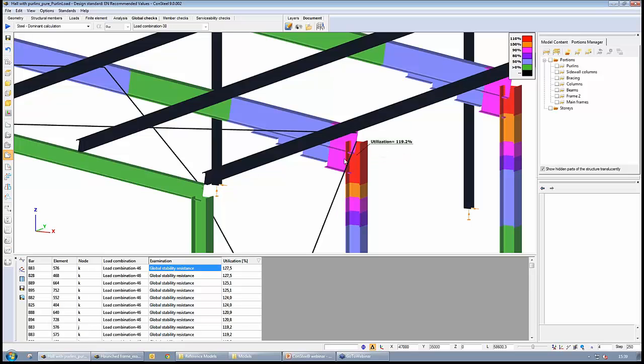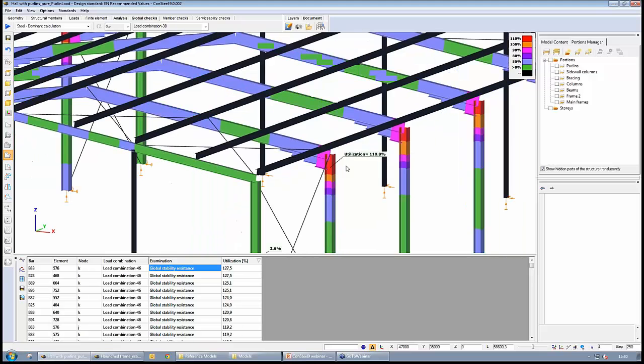It's some kind of shear panel behavior, a shear box, and the bending moment and the stability should be stopped at the end of this connection. For example, here where we can have a stiffener, and here where we have the end plate. So we have to apply only these values.